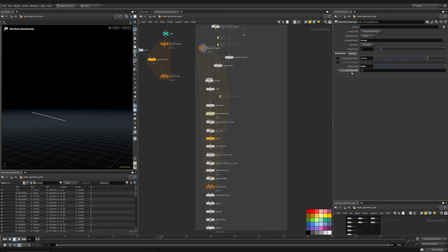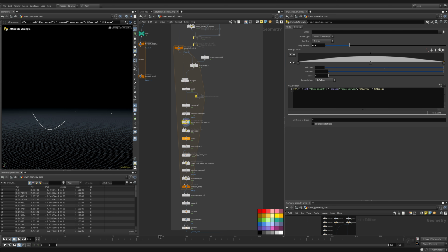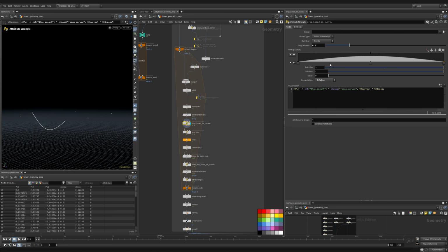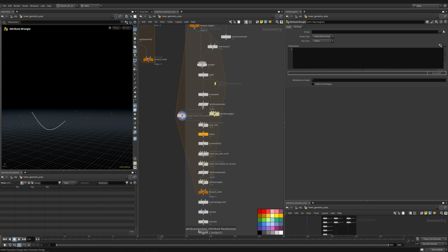That's what I do: I set the seed attribute for a droop value, which is a float between 0.5 and 3.5. Then I do a wrangle where I subtract by a remap and then multiply it by a curve. So I will show another way to set this up.